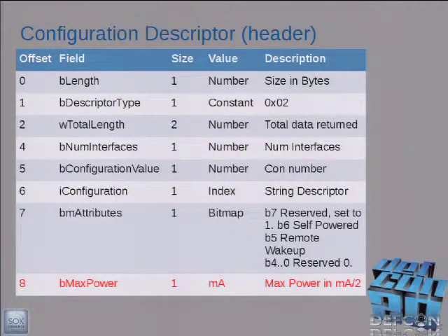So this configuration descriptor is gotten next, and again, it starts with the length, and then the type, which is type 2. They're real creative, right? 1, 2, etc. And it gives you some information. The last bit that it gives you is the maximum power.